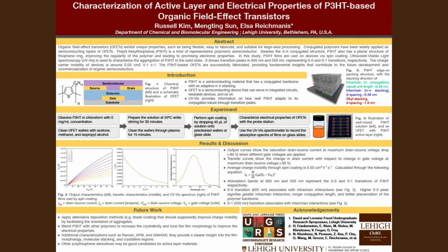Currently, we are exploring alternative coating methods such as plate coating and convective deposition, which should improve the charge mobility by facilitating the orientation of aggregates. We are also working with P3HT blends, predominantly PEO, polyethylene oxide, to increase the crystallinity and tune the film morphology to improve electrical properties.